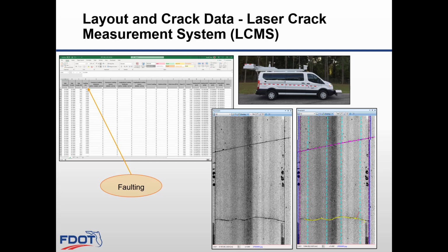This method is solely for capturing distresses on the slabs. This is used in combination with either photogrammetry or LIDAR for the survey purposes. The images can be georeferenced into the design file so the person analyzing the slabs can compare the output images to determine the appropriate corrective methodology for each slab.